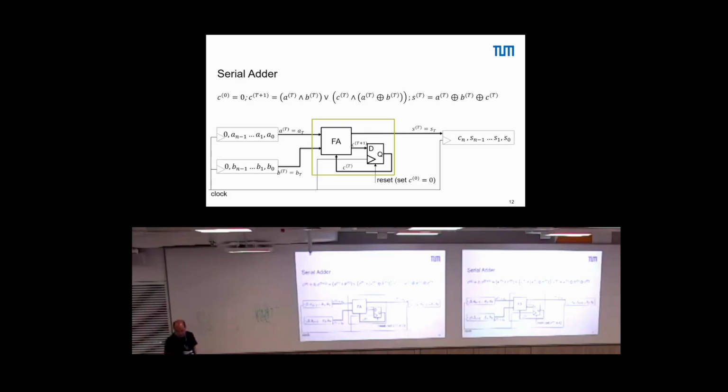So effectively, if you look into what we do on a circuit level, if we put A1 and B1 to 0 here, then we can interpret this as this side being blocked because there's a 0. Here's at least one 0, so this here is all 0, right? So the carry is then after the step 0. And AI XOR BI is 0. So whatever is the most significant bit is just the forwarded CI. Okay.